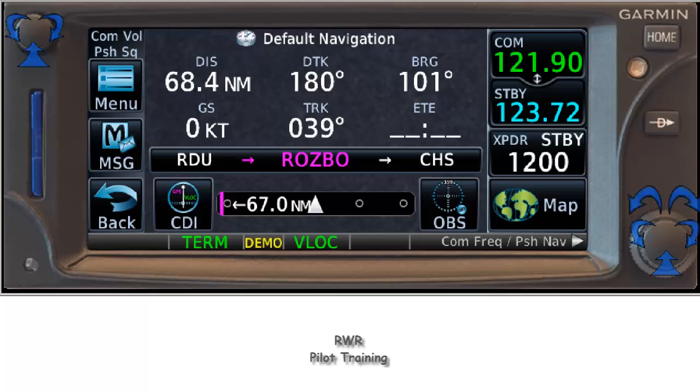And there is one last comment that I'd like to make. Some of the 650s are getting into the fleet. The side tones aren't properly adjusted, and or the auto brightness feature is either too bright or too dim. Both of those settings are settable. The side tone refers to how you hear yourself when you key the mic, not the volume of the audio panel, but when you key the mic, do you hear yourself in the headset too loudly, not loudly enough, or just right? That's called side tone.